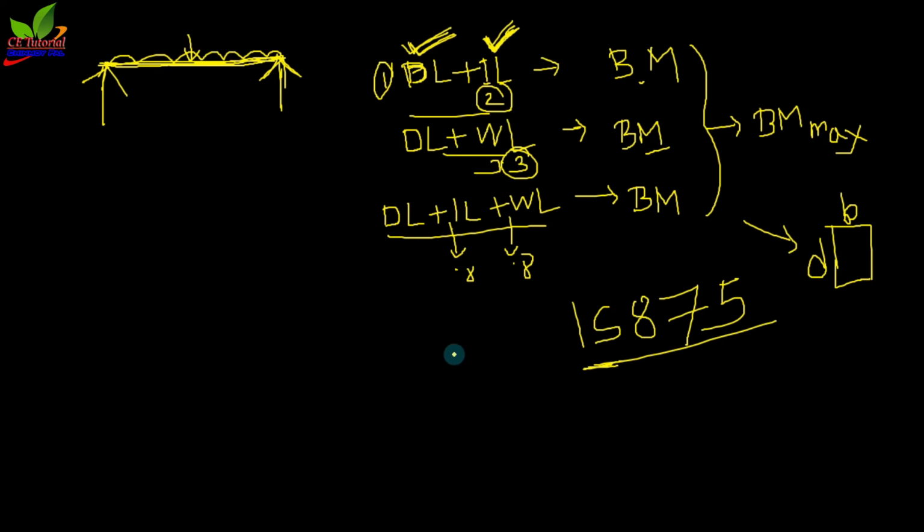In a hilly area, when snow load is coming, you can use part 4. Part 5 is the load combination, and special load cases plus load combinations are given in IS 875 part 5. Now what about earthquake load? There is another code for earthquake load. Okay, no issue.